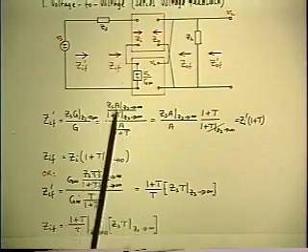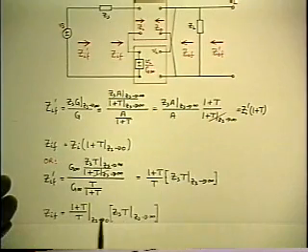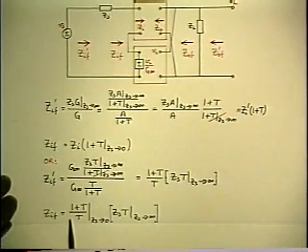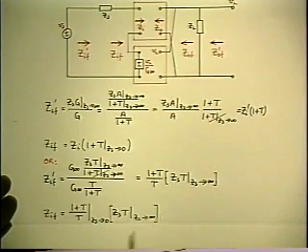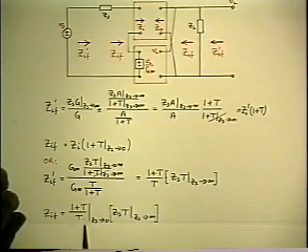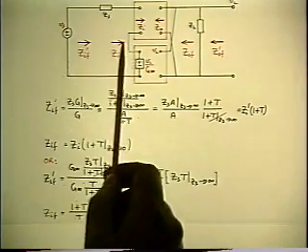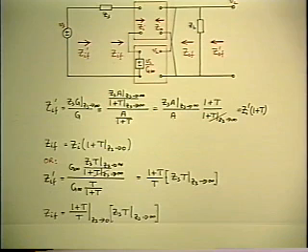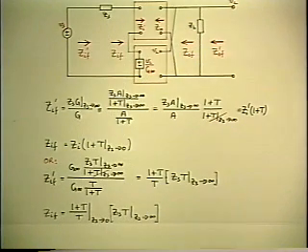And if you want the input impedance with feedback, take the other limit in the result, which means let ZS go to 0 in the first factor. It's already limited out of the square bracket, so that doesn't change. The only difference between the two is the factor in front, both of which are almost 1. So the inside and outside input impedances are almost equal with feedback. Therefore, both of them must be much bigger than ZS.